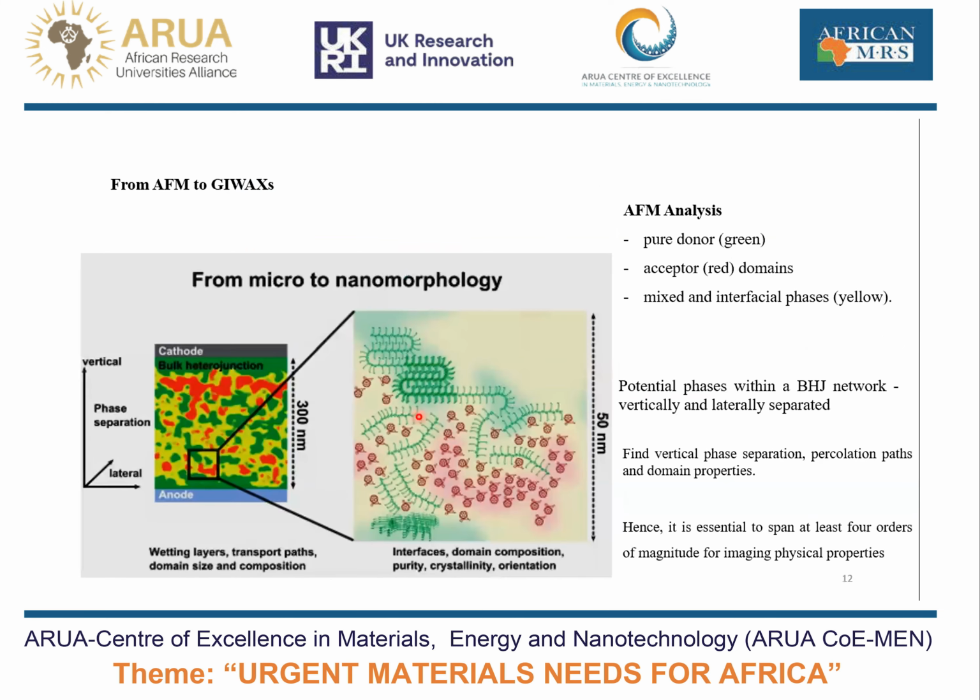Then we went further and looked at the morphology. We look at these materials in terms of structure, and this can be seen from a microscopic perspective to a nanomorphology aspect. From the microscopic perspective, we can look at this with atomic force microscopy, and you'll be able to see the wetting of layers, the transport paths, the domain size, and the composition of these domains within the material.